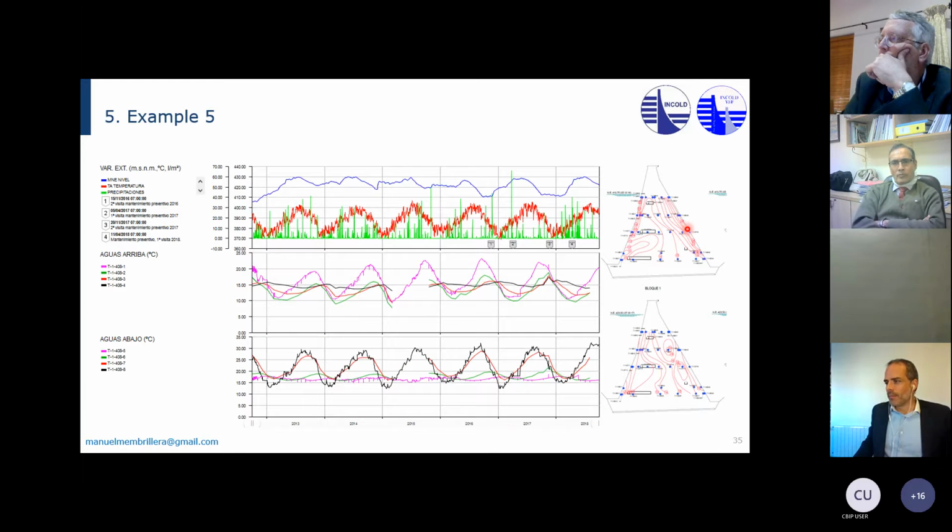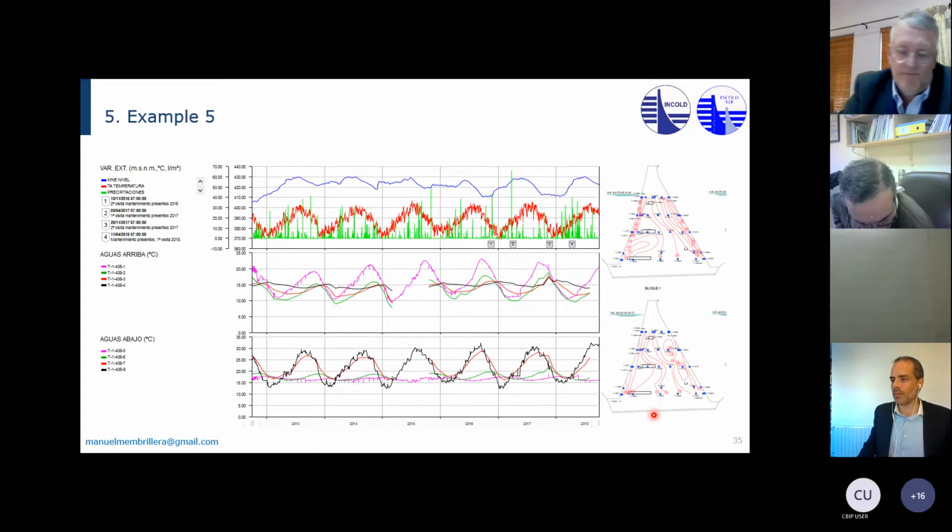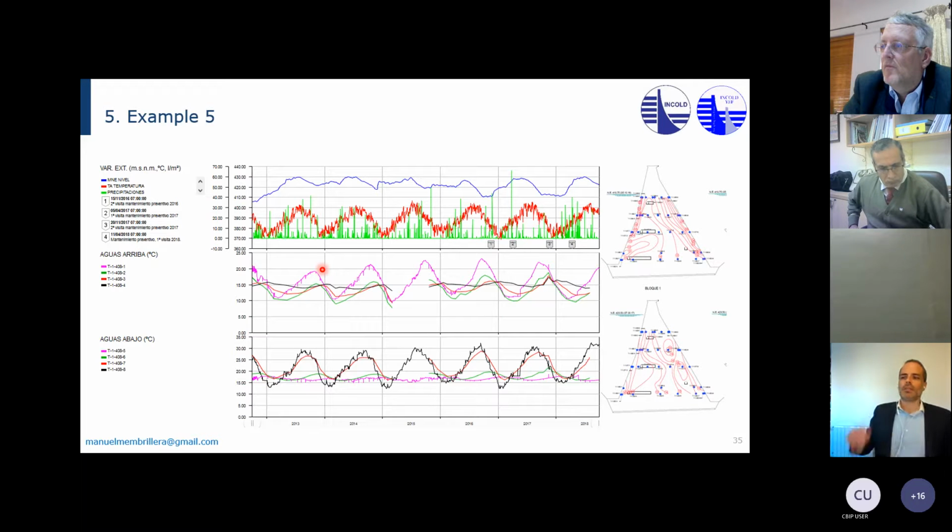You can see here also the lines with the same temperature. This focus on thermometers is because of cracking, and this internal cracking in the dam body can prevent the dam from behaving like one big element. And so you can see upstream and downstream and how the temperature is evolving with pool levels. This is 2013, 14, 15, and 2018. So, well, you can see just a few years here in the analysis.